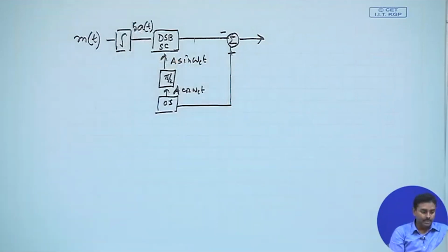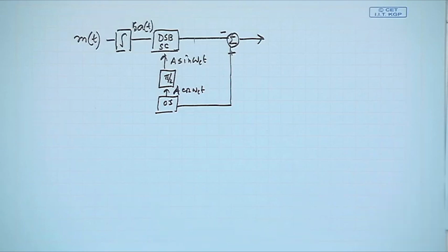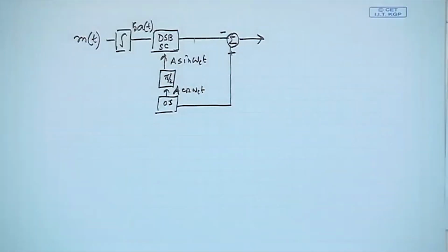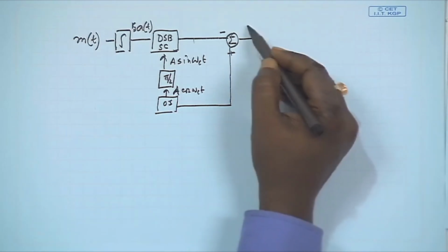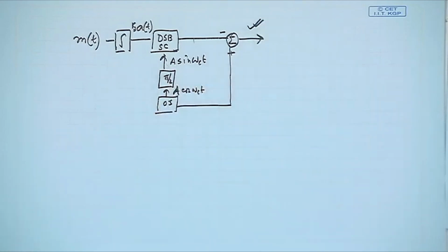So, wherever you wish to take that kf, it becomes like that. Okay. So, this is how narrowband FM works, as long as whatever kf you are choosing is small enough, or I should say kf into A(t) is small enough. If that is happening, you will not have too much deviation, and you do not really have to go and modulate the frequency with respect to the input signal, because we know that as long as that is small, we have that expression. Okay. So, immediately you will get FM modulation.